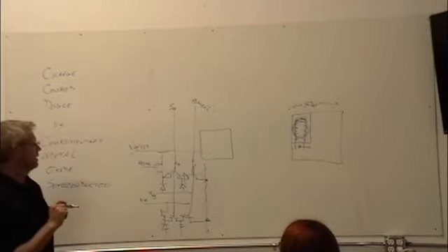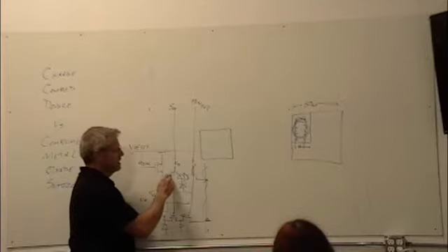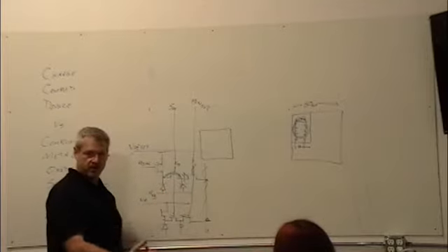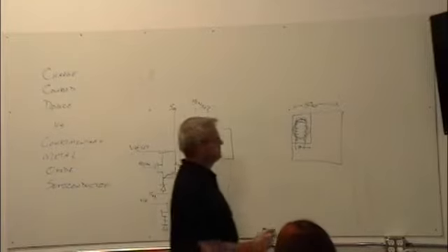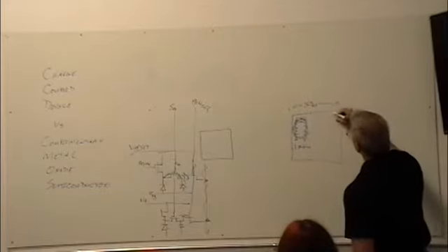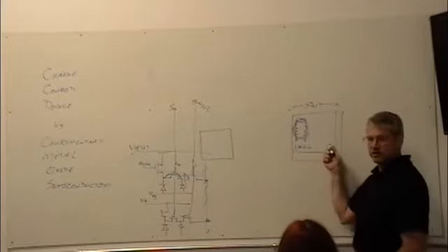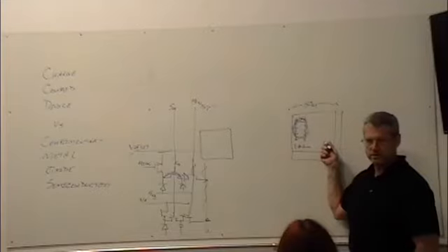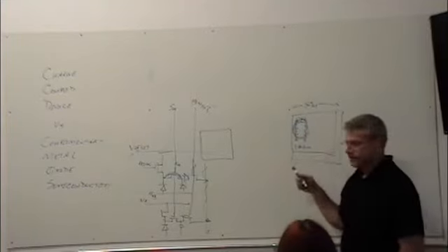I lose my train of thought, it's fun. So I've got more noise, but I can do this more often. Oh, wait a minute. Moore's law has come along, and now we're doing 0.15 micron transistors, rather than a 2 micron transistor. So that means now maybe this looks like this, and it's starting to challenge what a CCD was doing, area-wise, right? So now I'm getting a much larger collection area.